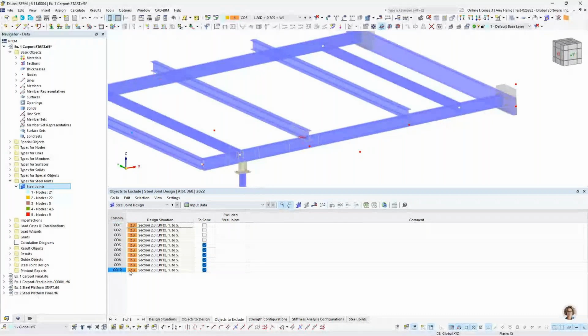And notice that you have the ability to uncheck load combinations. We are generating this submodel underneath the hood, and we are going to rerun each of these submodels through all load combinations. So it's highly recommended, if you know some of these load combinations are not controlling, to certainly uncheck them here so that we're not rerunning them in the submodel, taking up more calculation time.